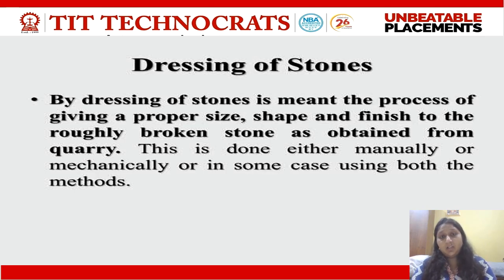But if I cut the stones as per my requirement, give them a shape and size as per my requirement, and then use them, such stones are called dressed stones. Hence, dressing of stones is a process to give proper shape, size and finishing to the stone as per your requirement. The dressing may be done either manually or mechanically or by a combination of both methods.